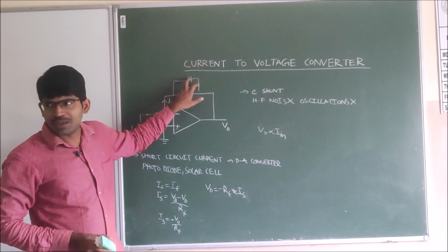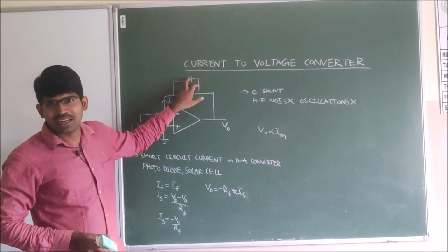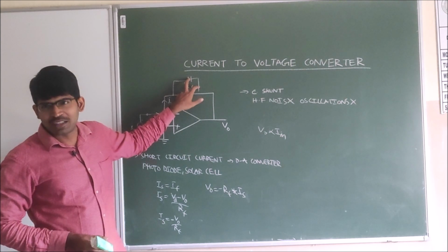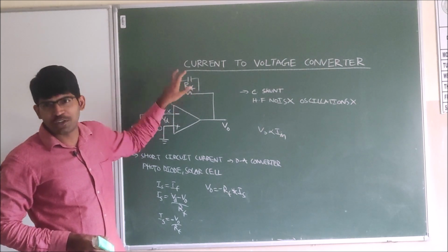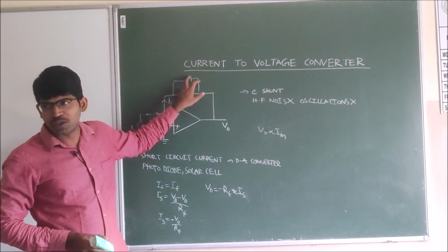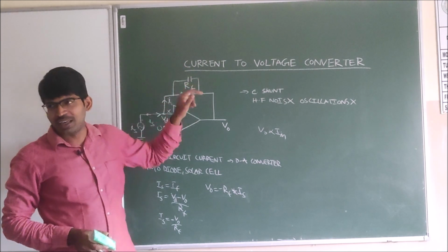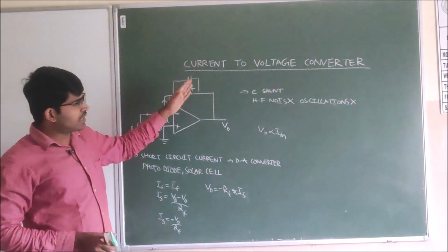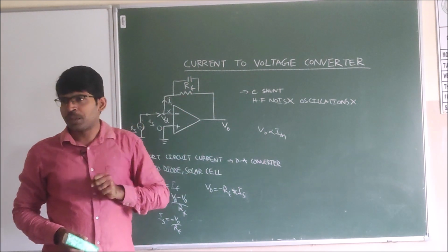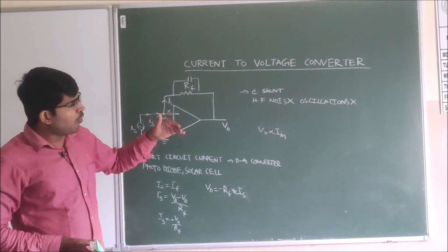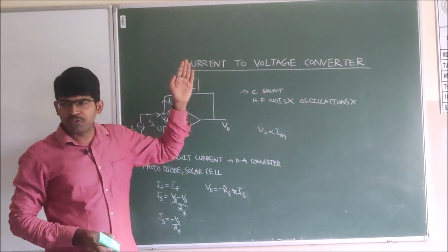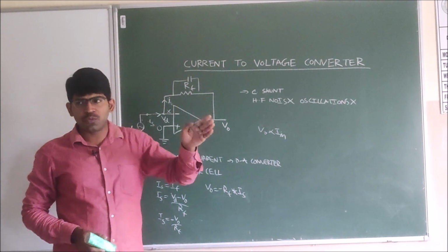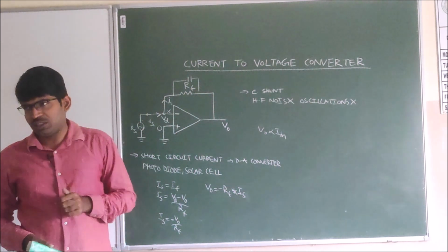If we use the capacitor, for the DC signal, the capacitor blocks. But when we send the high frequency signal, it will not go through the resistor, but it will go through the capacitor, because for that high frequency signal, the capacitor acts like a short circuit. So by simply shunting this capacitor across the resistor, we can avoid the noise effect at the high frequencies. We can avoid the output voltage being changed with respect to the noise at the high frequencies.